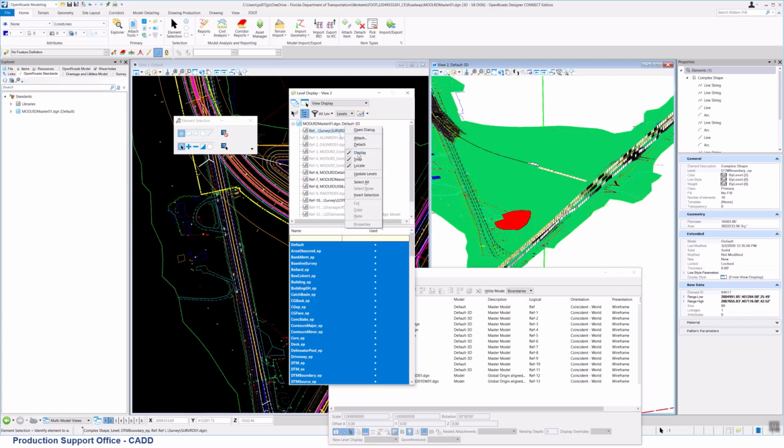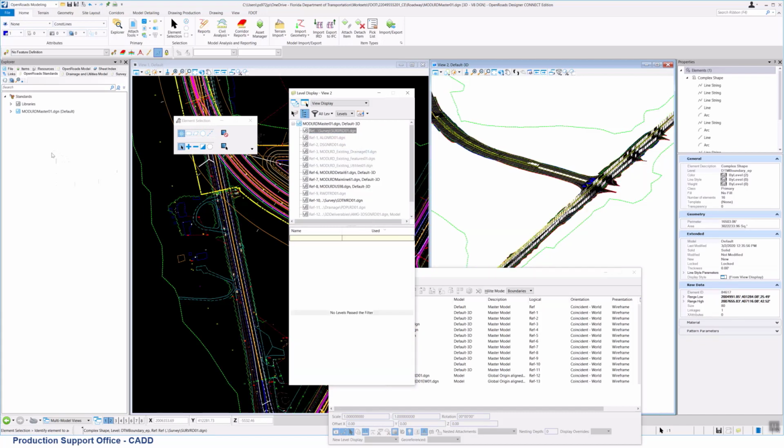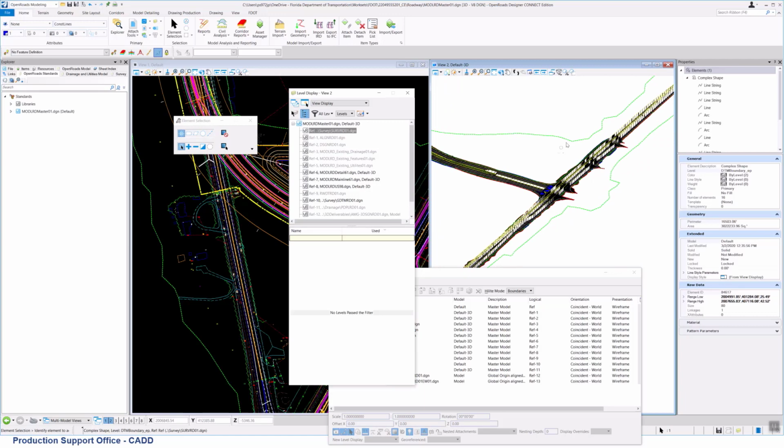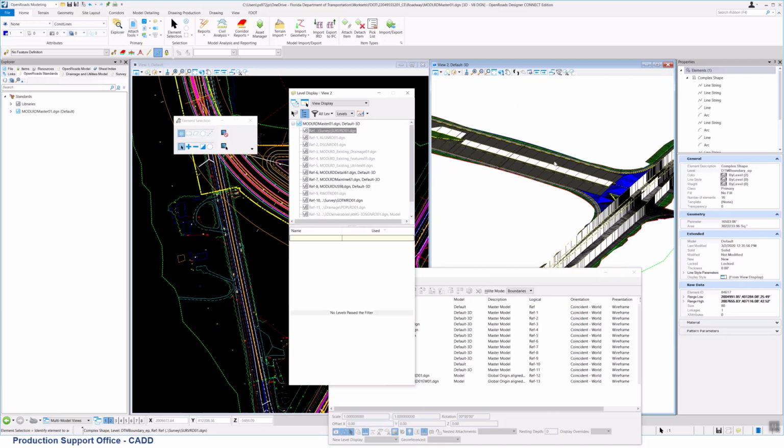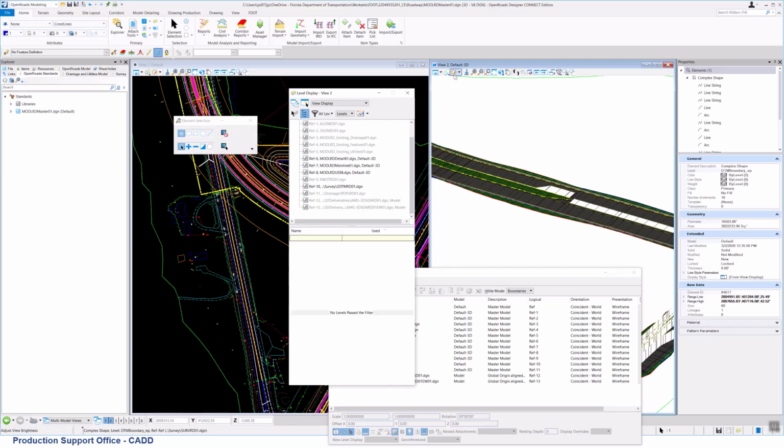And I don't think I can turn triangles on from a reference. I can't change the feature definitions from the reference to show you what it would look like with the triangles on. What we're going to do is basically clip it to the existing ground. The existing ground passes through here, and sometimes it's over here because of those cut and fill volumes. I just turned them off, but that gives you a sense of where that overlaps. If you have the existing ground, it's going to cover it up when you're trying to do visualization. So to visualize the finished product, what you want is existing ground only out here beyond the limits of this cut and fill, beyond your daylight lines basically, and that's it.